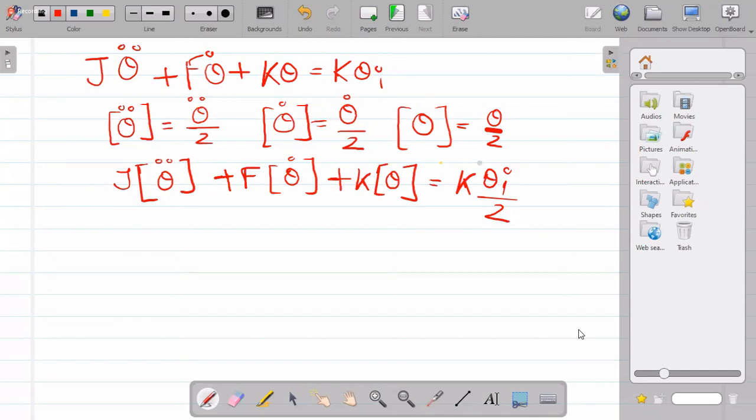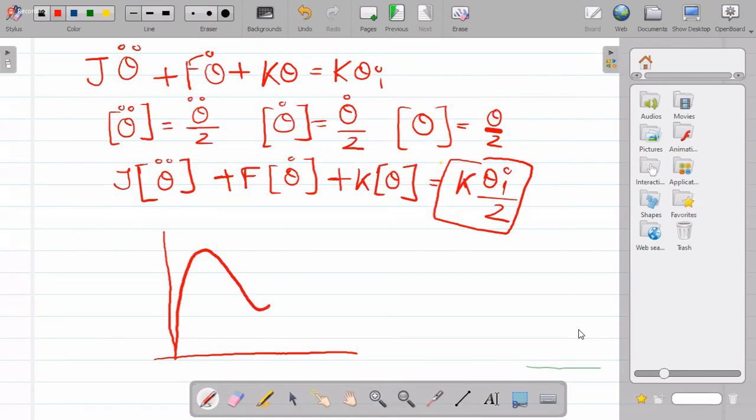So the actual input to the system, which was initially say a 10 volt step, will seem like a 5 volt step. So gains will remain the same, but under underdamped condition or any other condition, the peak value will only reach a value of 10 volt. Initially, it was reaching the maximum threshold value of 20 volts. Since it was a very simple and ideal condition where everything was just double, double, double, you can simply divide the actual value by 2 to obtain the scaled down value.